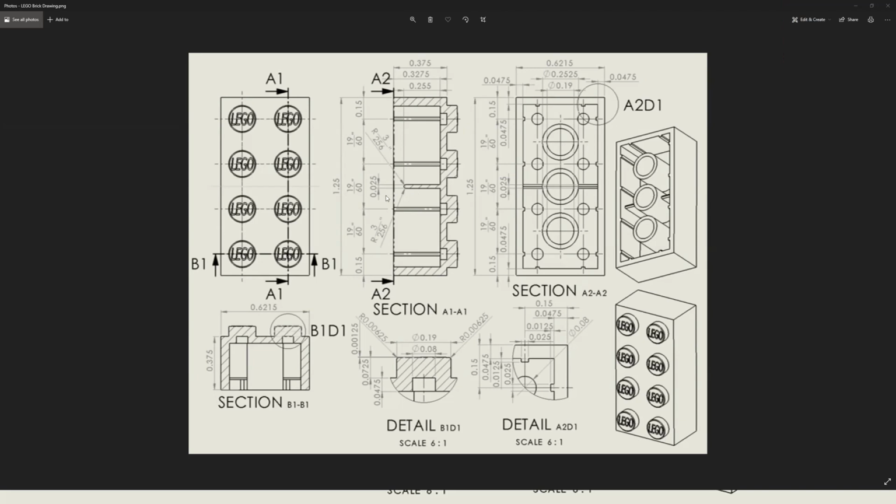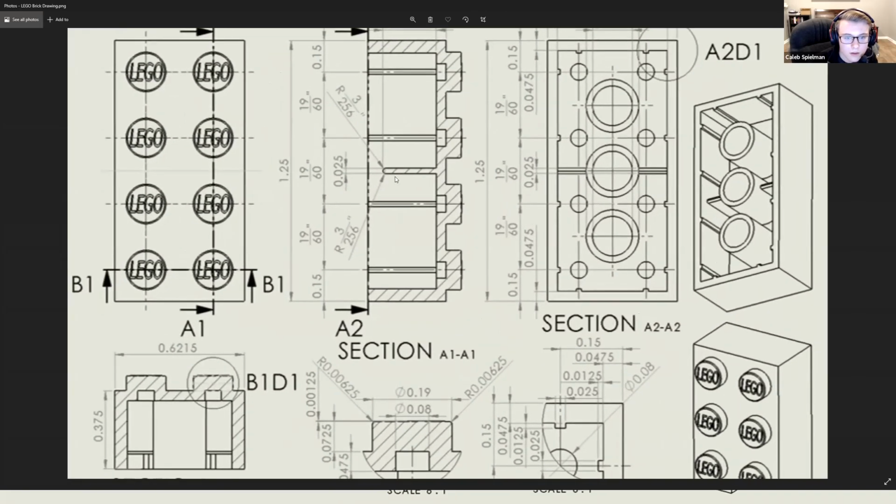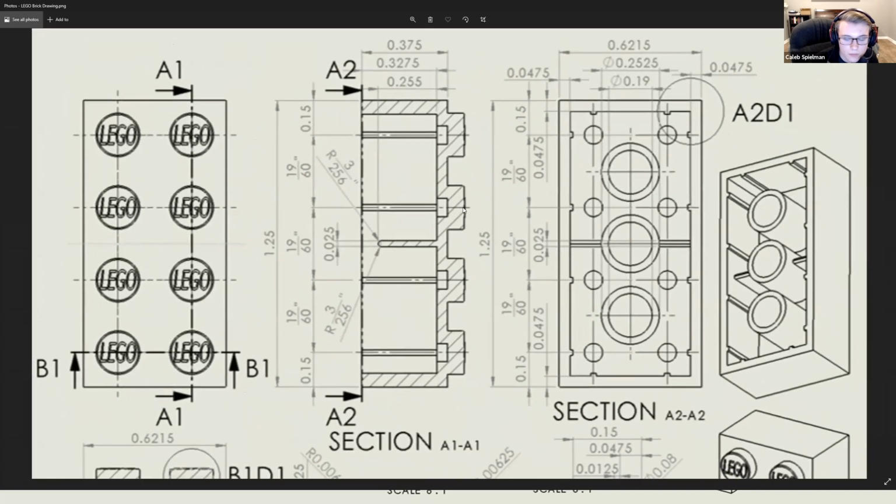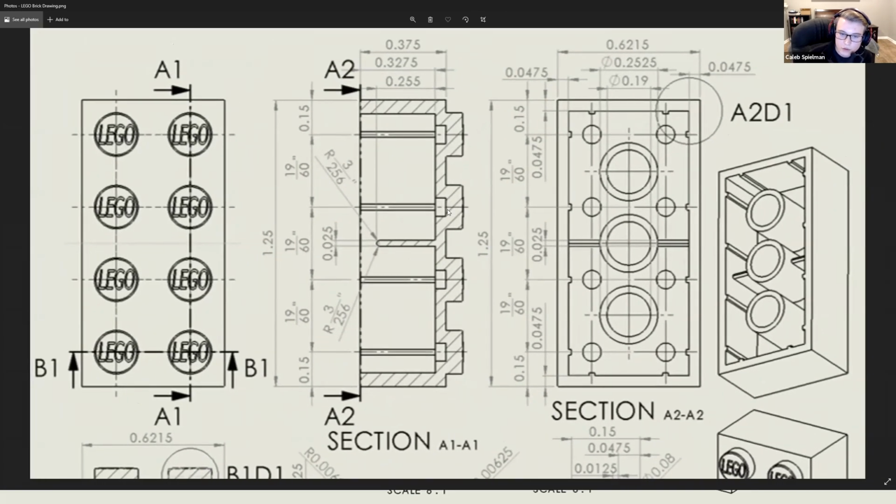All right. So here we have, reading a technical drawing for the first time. This is not very intuitive, but what this line here in the center means is that this cylinder and this cylinder are concentric. I'm having a hard time saying something other than concentric. That makes sense. So here we have this distance between the centers.